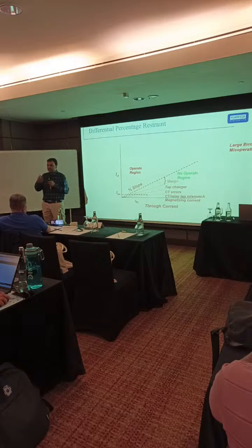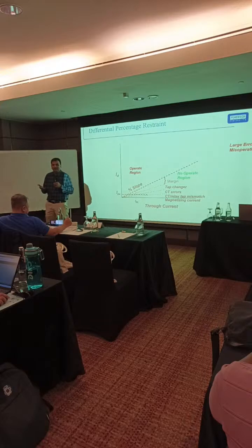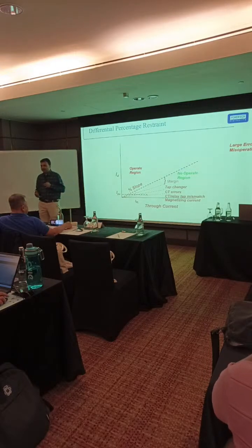You can easily find that out with modern relays. So you should not just blindly try to charge the transformer. It may damage your transformer. Without knowing the reason why it is tripping, you should not charge it again and again.